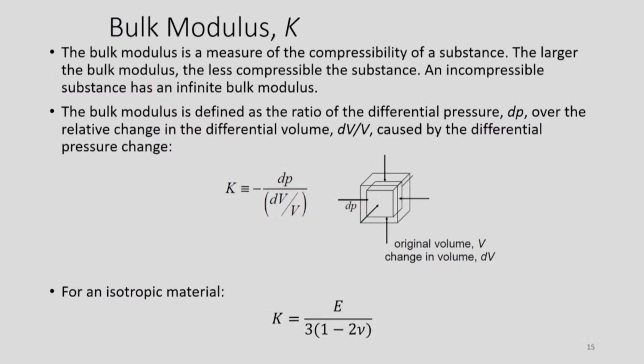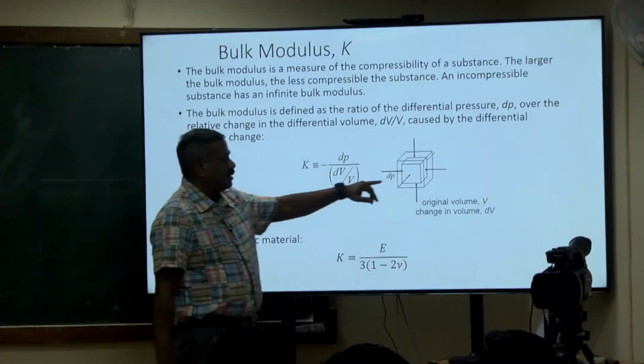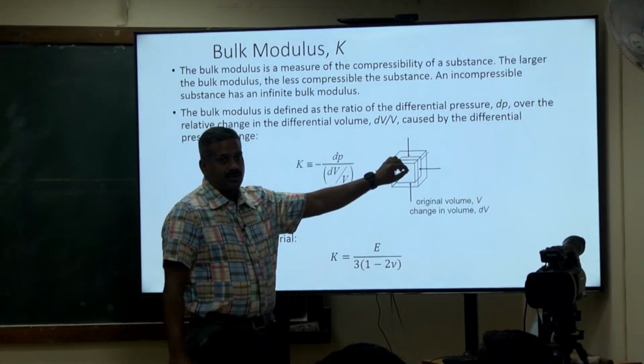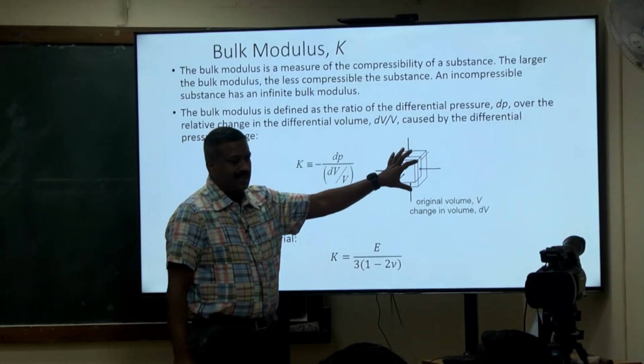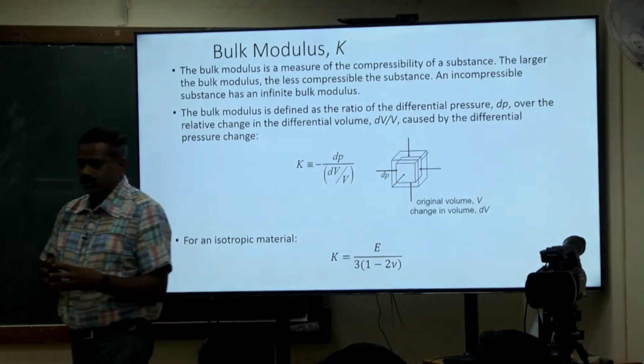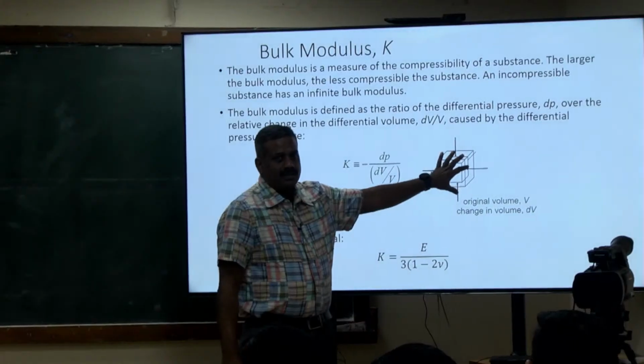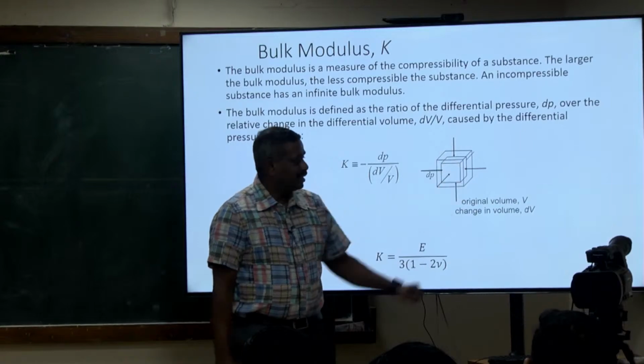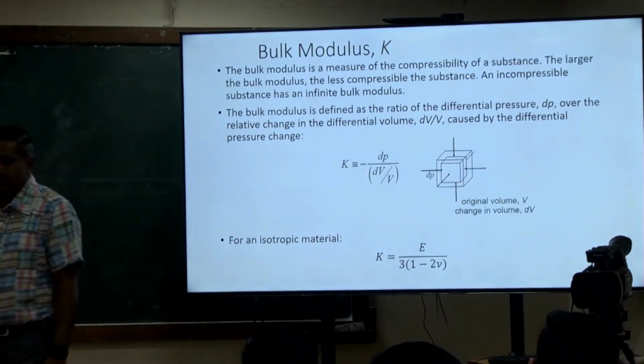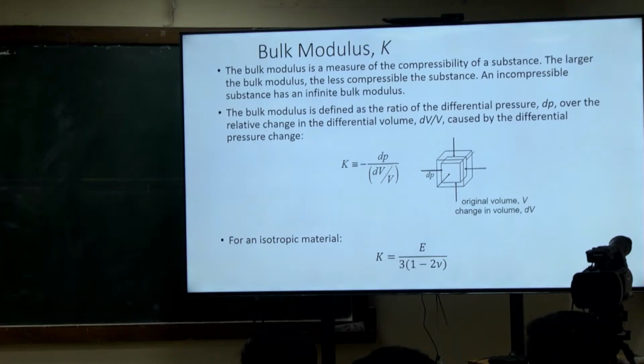Bulk modulus is mainly for compressing materials. It is the change in pressure and the change in volume. When you are compressing a material uniformly from all 360 degrees, it compresses in volume. That change in volume over applied pressure is the bulk modulus. Again, it is in the negative direction, so you might see negative values. For incompressible material, it is usually high negative. For easily compressible material, it is low negative values.